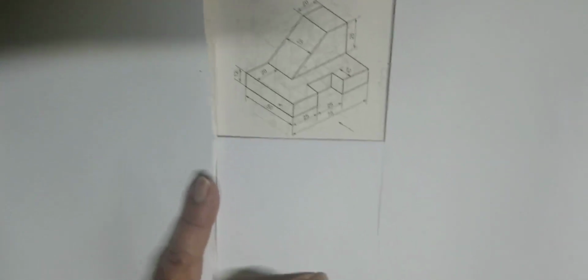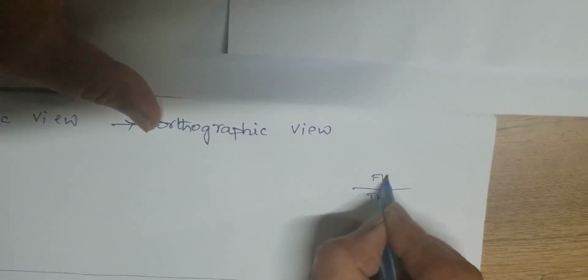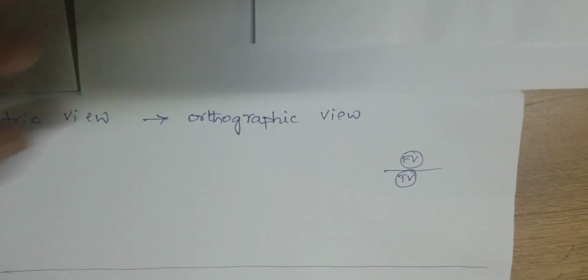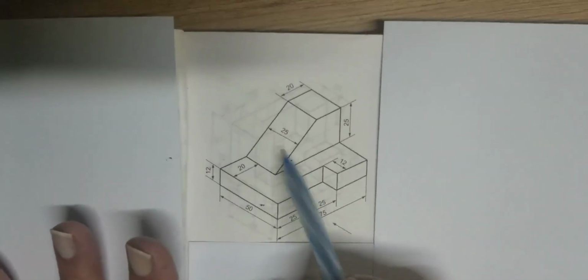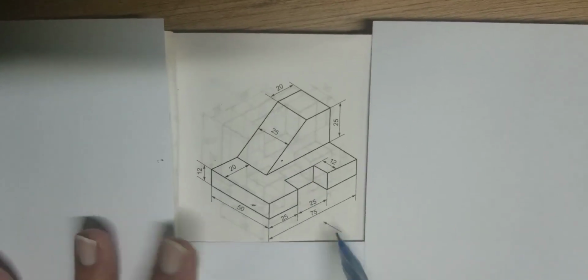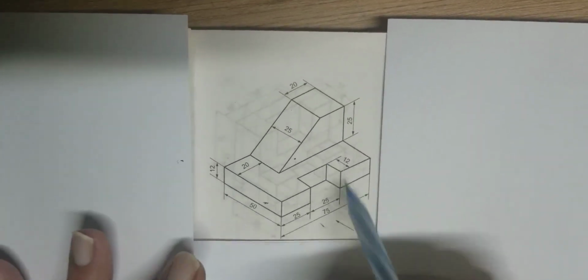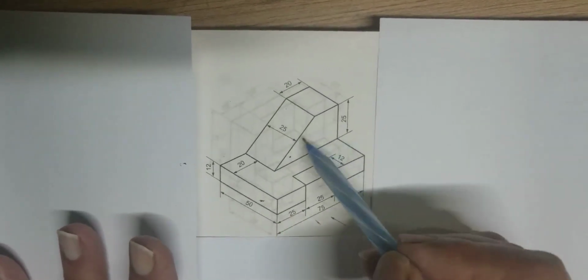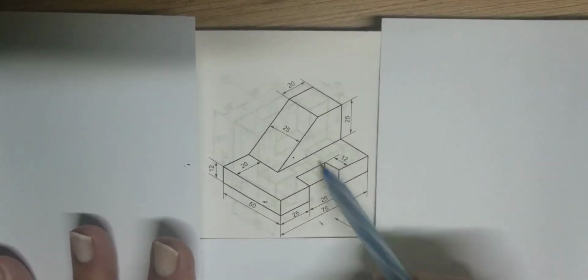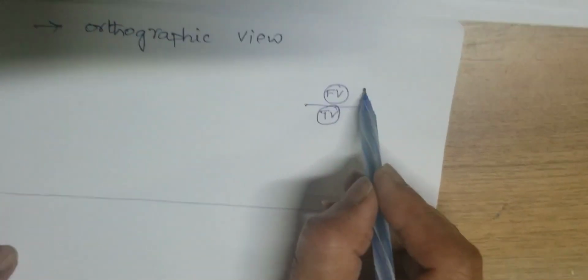That means, very roughly I will explain here. If it is the front view, the top view we have to write at the bottom, front view above, top view below. The side view you have to write either left side or right side depending upon the component that is given. So see here once again by going to the question, the left side of the side view is visible. If it is the front view, top view and side view, this left side is visible. When left side is visible, we have to draw the right side of the component, right side of the front view. See here. That means here we have to draw the side view.